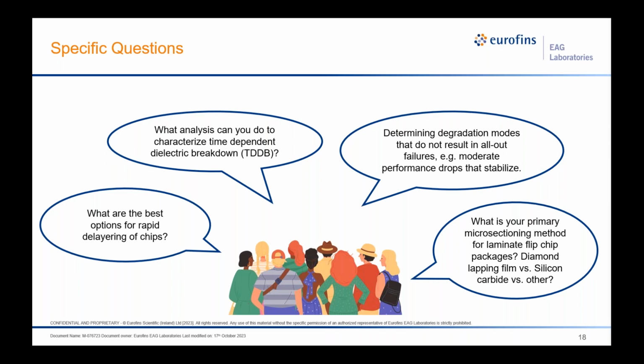So there's actually not a great specific answer to this, other than the fact that there are a lot of different factors that you have to understand, and one of them would be the technology node. You have aluminum unplanarized processes, which are kind of old, and the newer processes are copper dual damascene and CMP planarized, and now some of the more advanced node technology is FinFETs and low-K dielectric. So knowing the type of sample that we have is important.